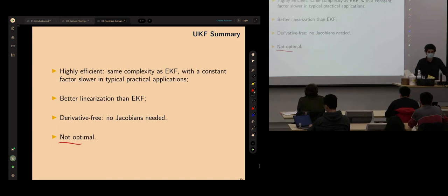Again, in the invariant Kalman filter, using the exponential coordinates, you see that we can get constant Jacobians. Well, then it doesn't make sense to use UKF. Maybe it does, maybe you can get slightly better performance. But if your Jacobians after linearization in certain coordinate transformations become constant, that looks a lot like the linear Kalman filter, right? So that still motivates us to use that.